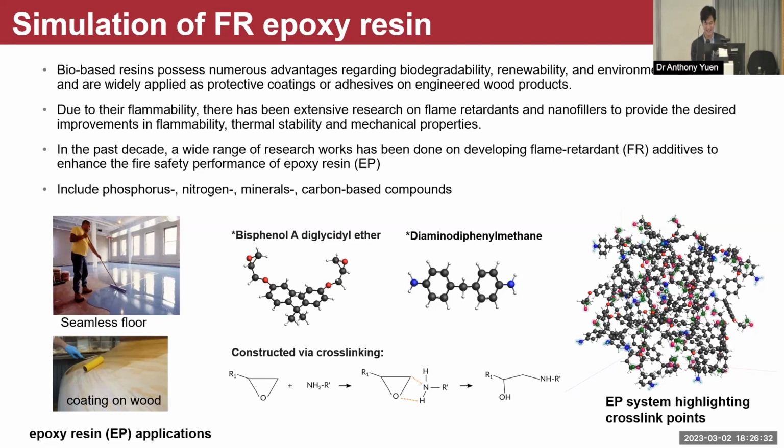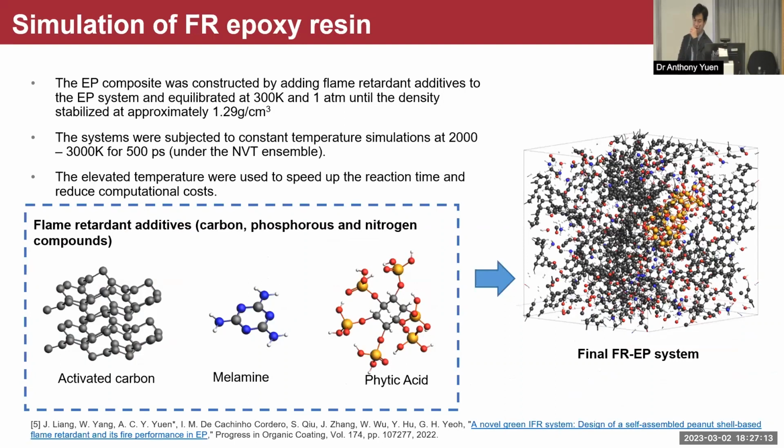So we try to understand the flammability of epoxy first by doing a very simple study. But first, in the MD simulation, we need to replicate the chemical process to formulate the epoxy structure itself. So you need the basic component on your left. You need the hardener and then the cross-linker. What the cross-linker does is link up these two components, and then it formulates the chain structure. And then again, we do the amorphous structure formulating process to formulate this nice epoxy here.